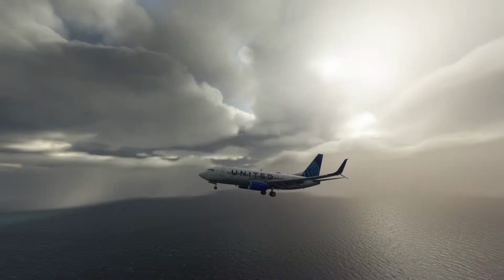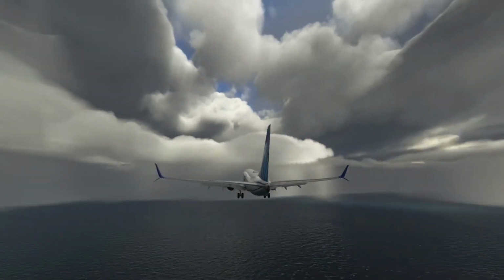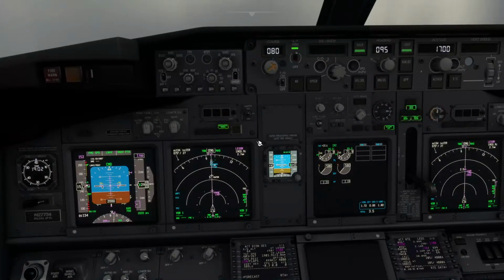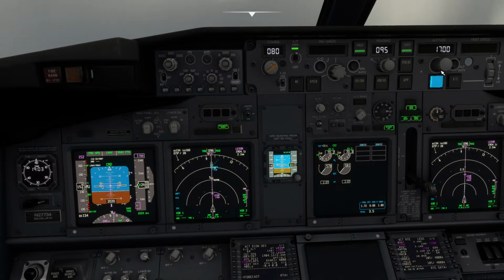I hope I can see this runway, man, as the rain is right in front of us. And remember, the 737, there is no automatic go around if you are shooting any other approach than an ILS approach with dual autopilot coupled. So okay, we are getting close to the FAF, so minimas are 750, so let's call it 800.